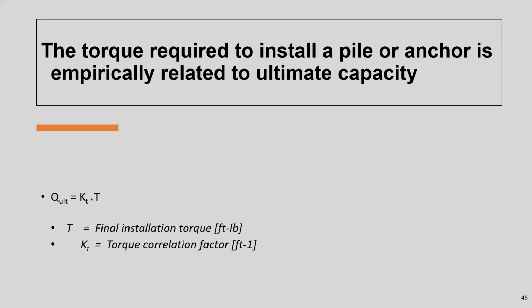They did 97 tests, all of them in tension, and they used 8 different shaft sizes, from 1.5 inch square shaft all the way to 8.625 inch outside diameter shaft. They used 24 different test sites and different helix configurations. They used the individual bearing plate method, the cylindrical shear method, and the torque capacity correlation method. When they tested them, they came up with the ultimate pile capacity.